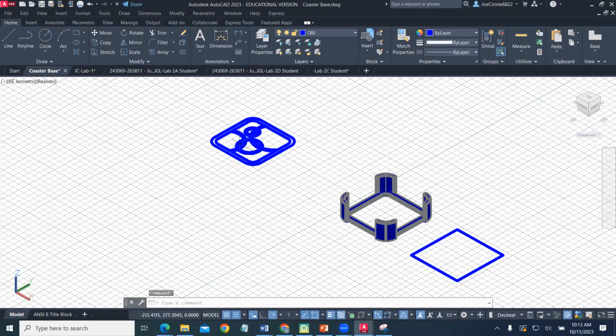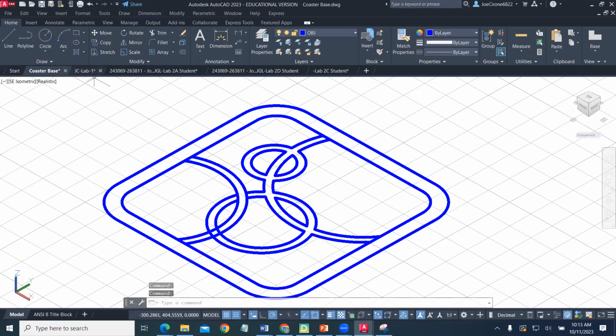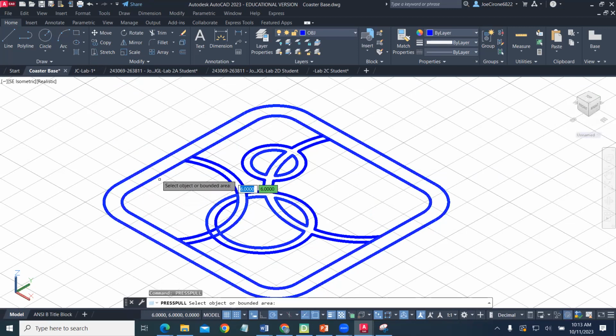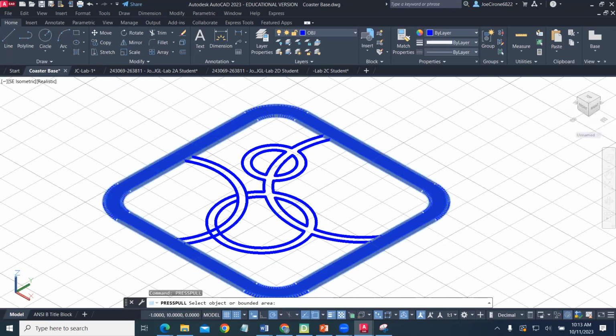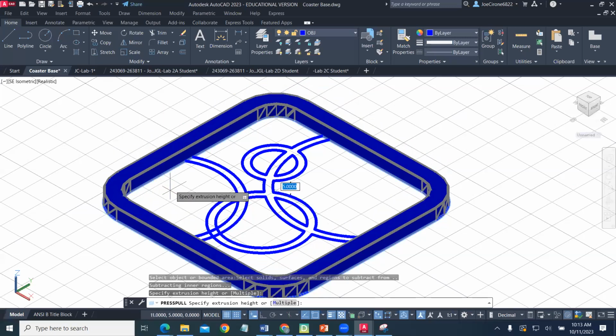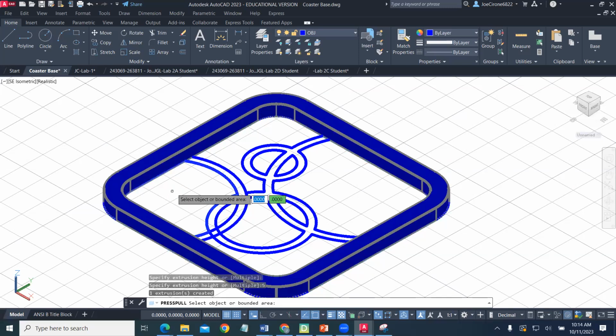And so here's an example of our last project. And it's the same techniques where we go through, we model it in AutoCAD, and then we can use press pull to design for 3D printing. And so when we use press pull, we can grab the geometry, we can pull that up, and you can see this is why we want things connected, because I'll have to press pull more than one element. So if I press pull that up 5, and then I can come in here and press pull this one.